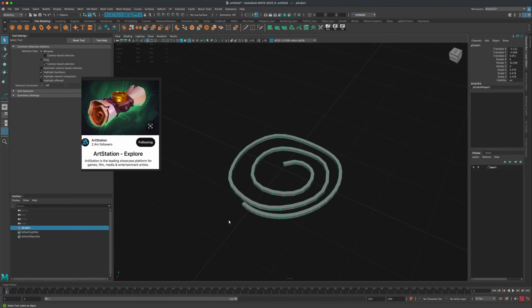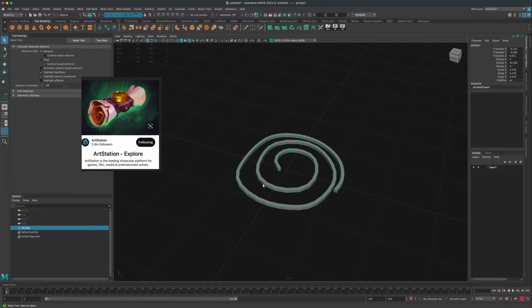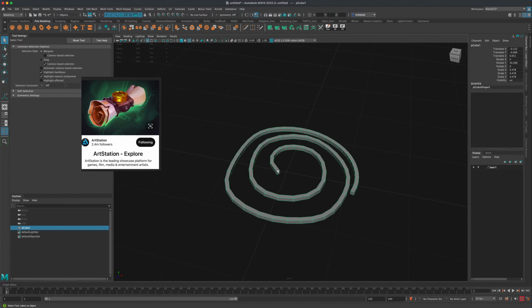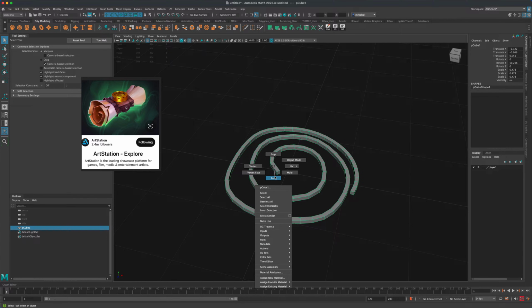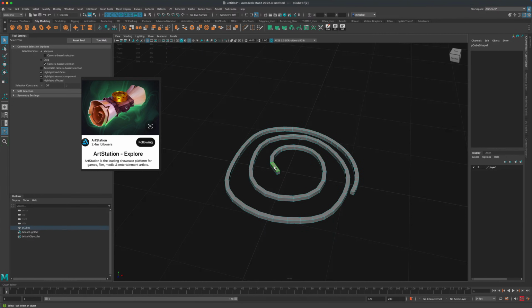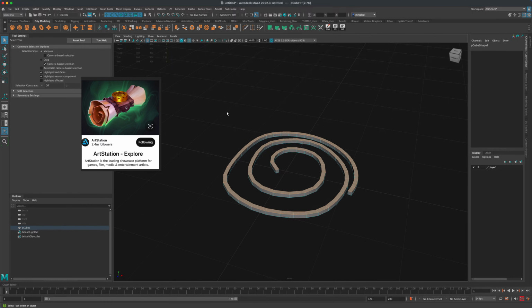And now what I would like to do is extrude this paper up, essentially creating the cylinder, right? So let's go ahead and do that. I'm going to go to face mode, click on this face here, and then follow the loop and end right here. So I'm going to hold the shift key and double click. All right.